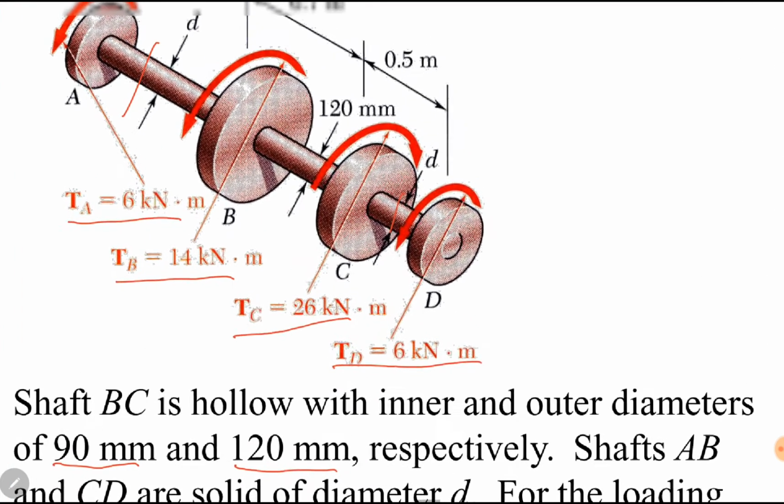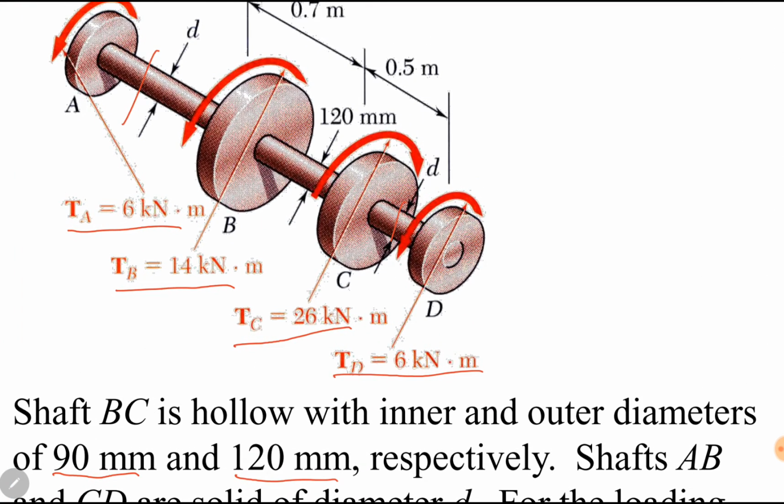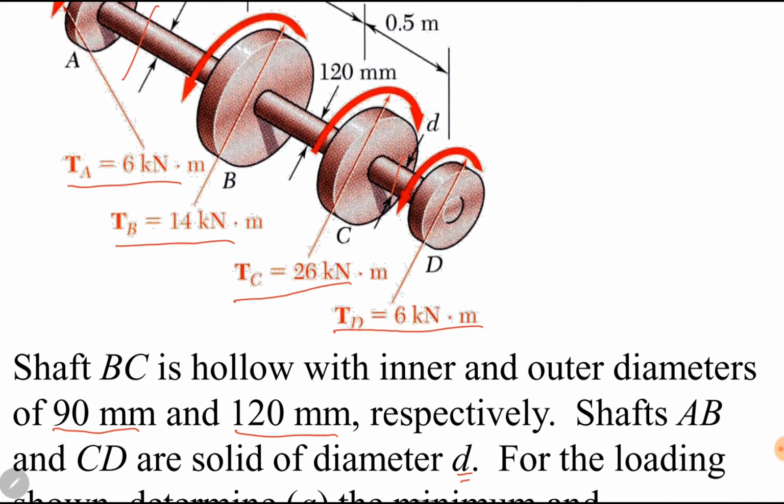So in the center shaft, we have to find minimum and maximum shearing stresses. Since it is a hollow shaft, minimum shear stress is at the internal radius and maximum shear stress is at the external radius.